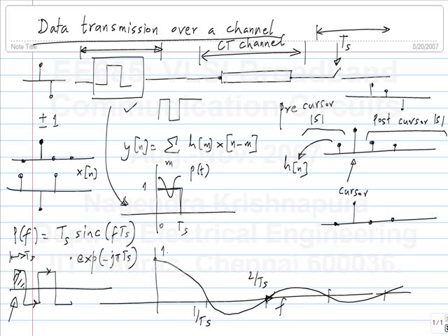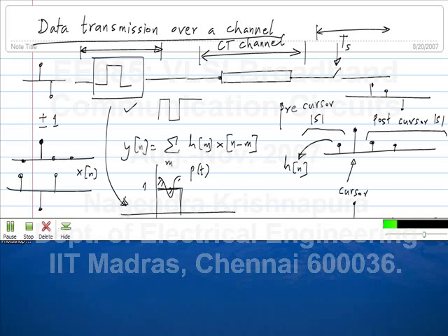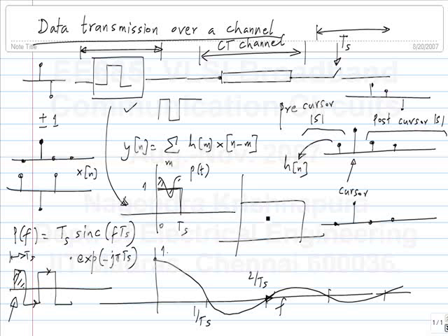Okay. So take a sinusoid of any phase, which is an integer multiple of fs. You will have one full cycle and the integral will be 0. You take a pulse and you can take a full cycle like this or with any other phase, the integral will turn out to be 0. And the same holds for harmonics of fs also. Because if you hold a waveform constant for Ts, then you multiply it with the sinusoid whose frequency is fs and integrate it, you will always get 0.